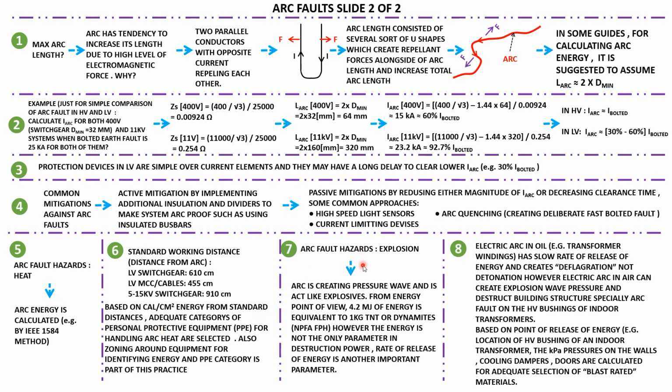The other hazard of the arc, which is not very well known among engineers, is explosion. In addition to heat, an arc can create an explosion, and this kind of pressure wave could damage the structure, could damage the wall, and bring some sort of hazard to people, by collapsing the buildings or equipment. And that is different from the heat. It's an explosion.